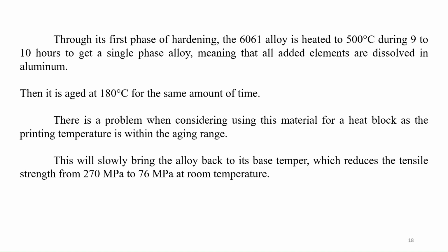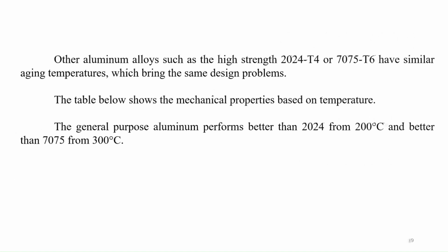There is a problem when using the material for the heat block, as the printing temperature is within the aging range. There will be a slow aging of the alloy back at a base temperature, which reduces the tensile strength from 270 megapascal to 76 megapascal at room temperature.